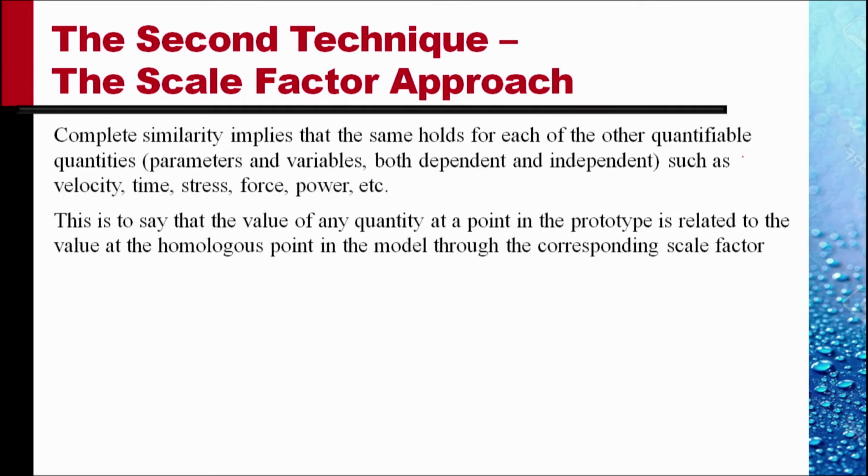Complete similarity implies that the same holds for each of the other quantifiable quantities, parameters and variables, both dependent and independent, such as velocity, time, stress, power, etc. This is to say that the value of any quantity at a point in the prototype is related to the value at the homologous point in the model through the corresponding scale factor.